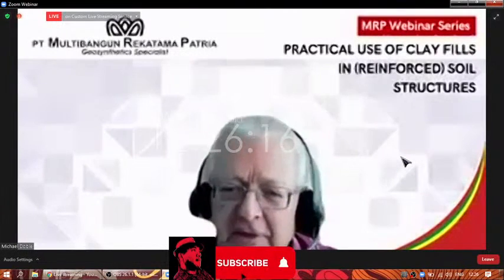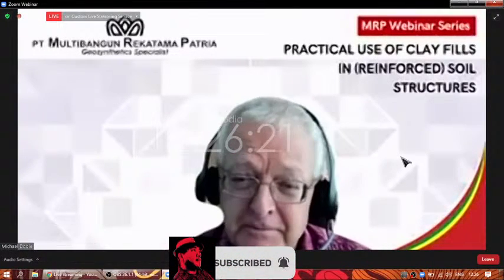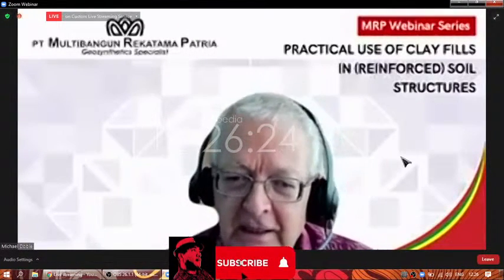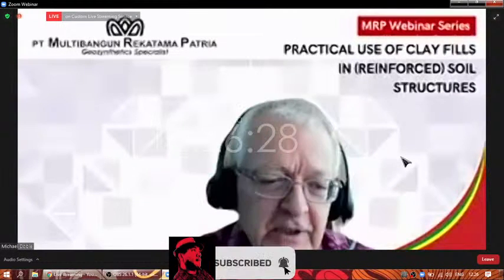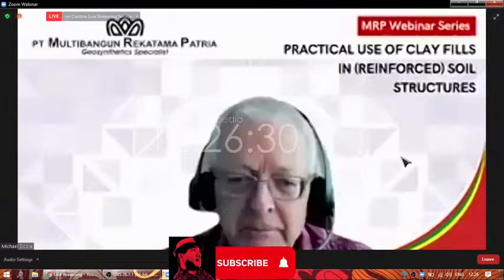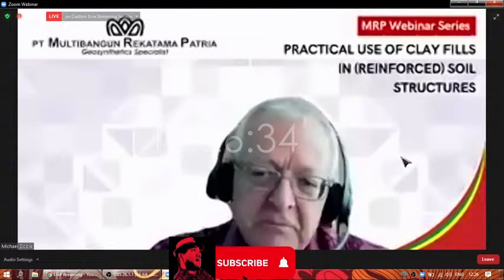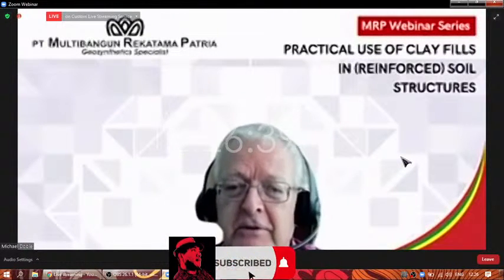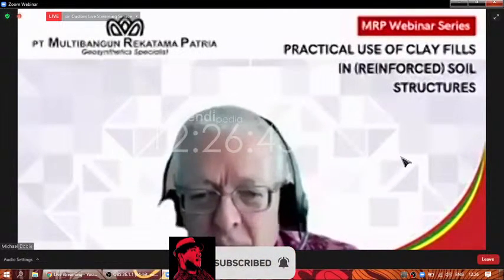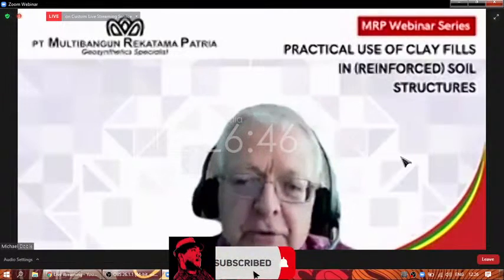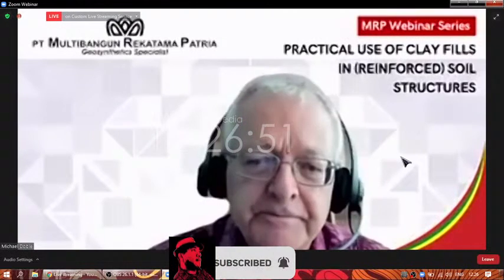Clay's permeability is incredibly small. So if you do have water sitting on top of a clay fill, it doesn't rush in. It'll certainly soften up very, very close to the water quickly. But if you scrape that away down a few centimeters, you'll find it's unaffected, unless the water stands there for a very long time. So I think the best way is to arrange surface water drainage and crossfalls to minimize contact of water with clay that's in suction.